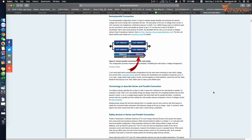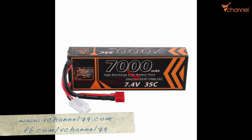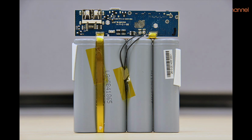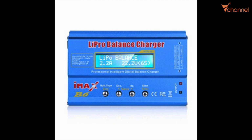At the market, you can see batteries labeled 2S2P. This is just serial as well as parallel connection. 2S is 2 cells in series. 2P is 2 pairs in parallel. Connecting many battery cells to create a new battery causes some problems. The cells will no longer be uniform in using and in charging, and that's the reason the balance charger was created.